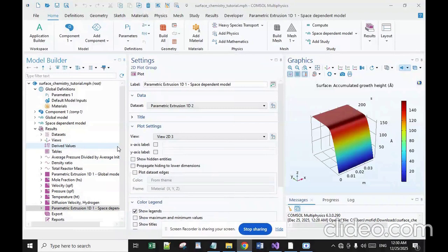Today I want to talk about surface chemistry using plasma module. Chemical vapor deposition, or CVD, is a crucial materials processing technique where volatile chemical precursors react or decompose on a heated substrate surface to form high quality solid thin films or microstructures essential for semiconductors, optics, and advanced materials, by delivering reactive atoms to the surface while removing gas byproducts.